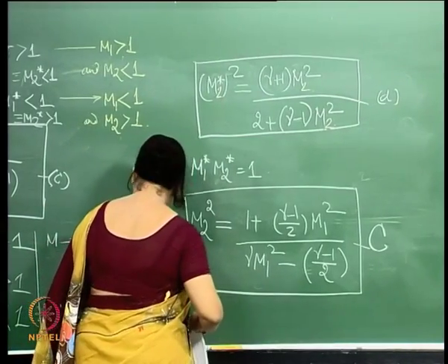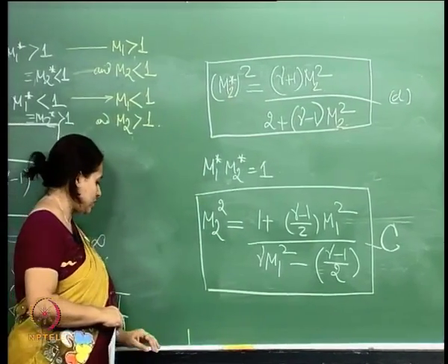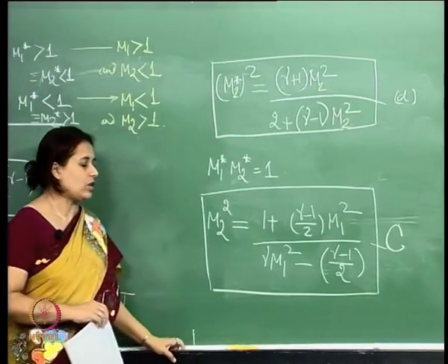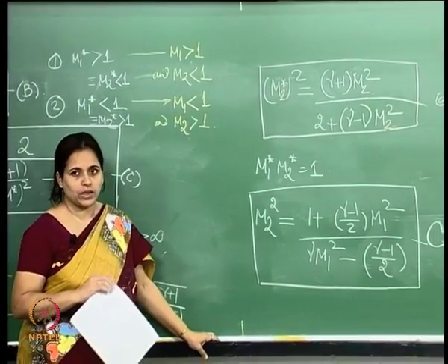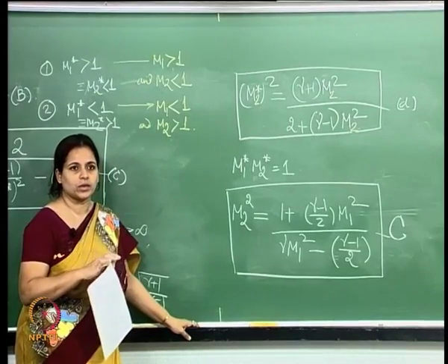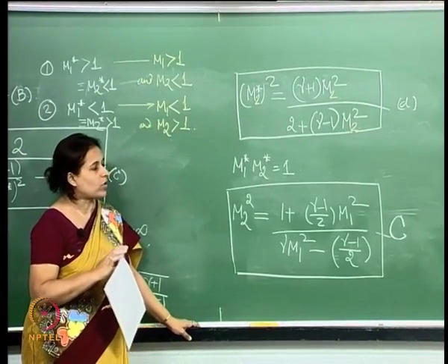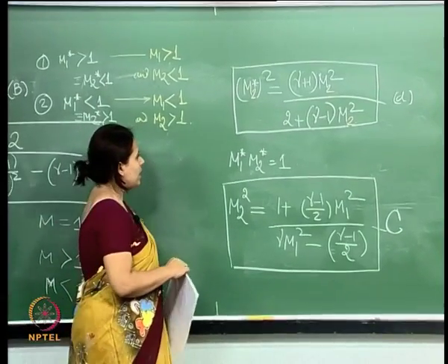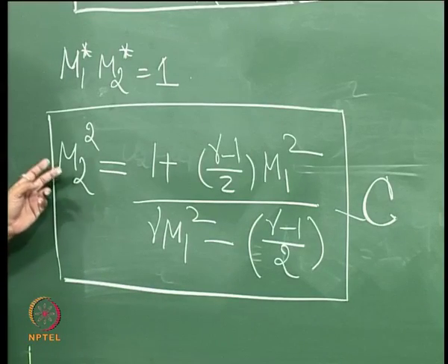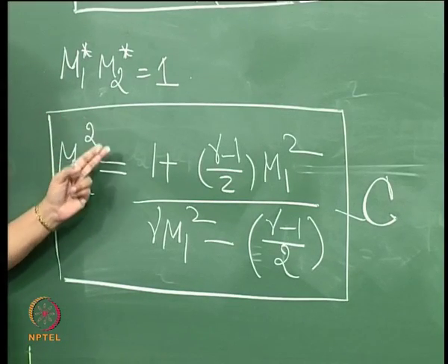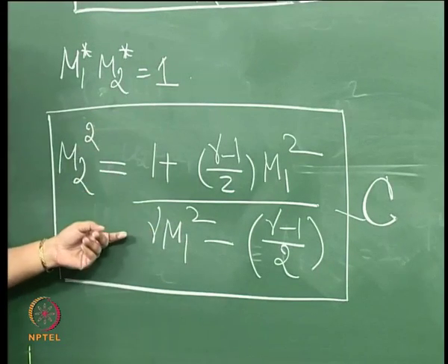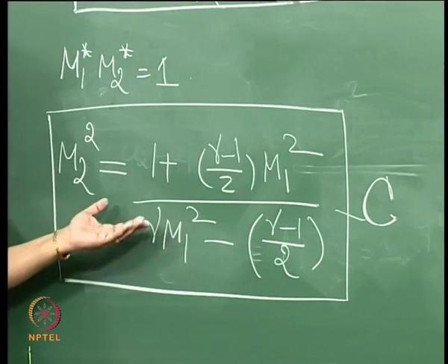Okay. So, now that we have done this, although we haven't answered the question, like we said, whether supersonic flow slowing down to subsonic flow will cause a shock wave or vice versa. What we have done in this equation is that we have written out the Mach number in the region after the shock in terms of the incoming Mach number.